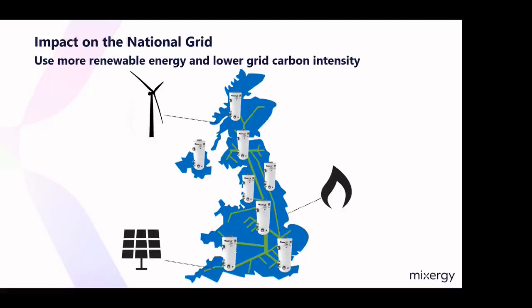So for example, within 100 milliseconds, the tanks can join up and take 1.5 megawatts of capacity. All the immersion heaters switch on to balance the load on the grid, and there's a benefit to the customer that can be taken in 2 ways. If the customer is paid to heat the hot water on an agile tariff, or through machine learning for non-agile electricity tariff customers, the electricity used and the hot water created during the DSR event can be offset against their normal schedule, so that it offsets the cost and reduces their carbon footprint. So in net, it doesn't cost them anything.